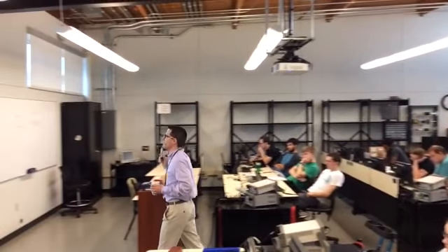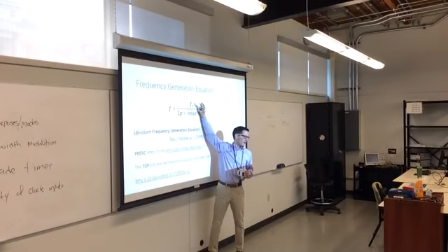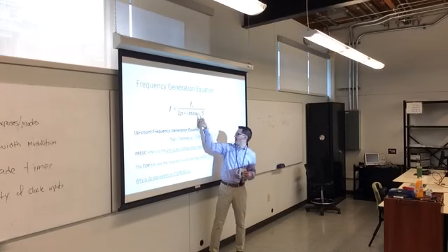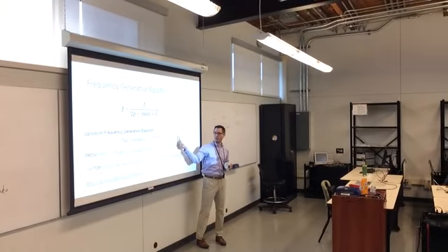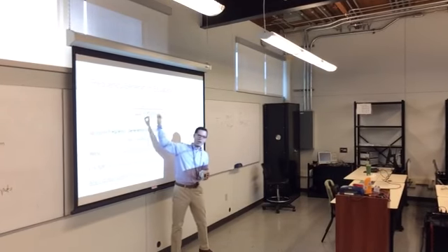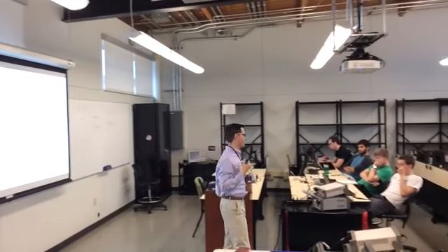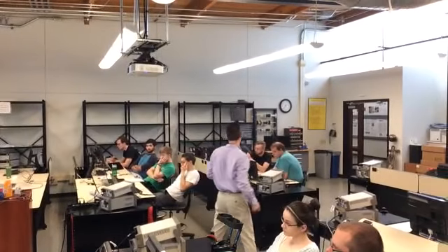I just represent these quantities differently. In my equation, here is the incoming clock frequency, FC. Here is their incoming clock frequency. This is my idea about the maximum value plus 1. Here's their idea of the maximum value plus 1. The major difference is that I represent the prescale as an integer: a prescale of 1 means don't do anything to the clock, and a 2 means cut the clock in half, and so on.